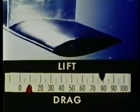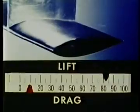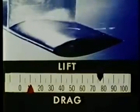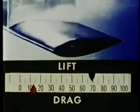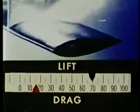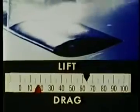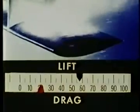We are going to induce cavitation by decreasing the ambient pressure in the test section, keeping the speed constant. At first, there is no appreciable change in either force. As cavitation develops, lift decreases and drag rises. You can see from the force balances that the flow is quite unsteady. When we lower the pressure further and allow cavitation to spread, the lift decreases further and the drag continues to rise.